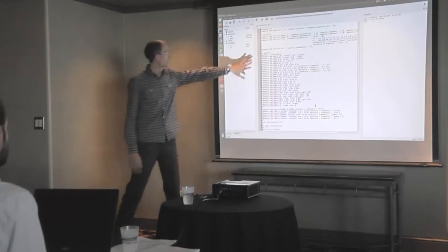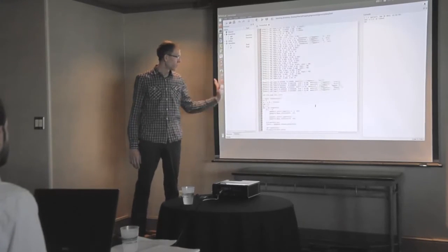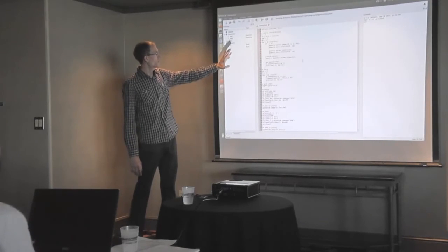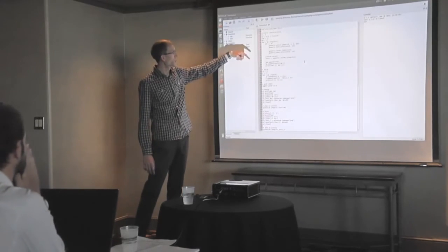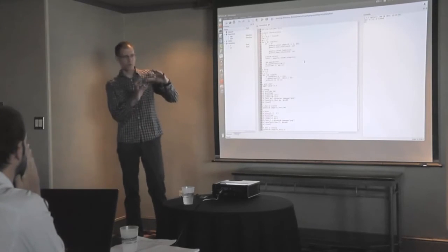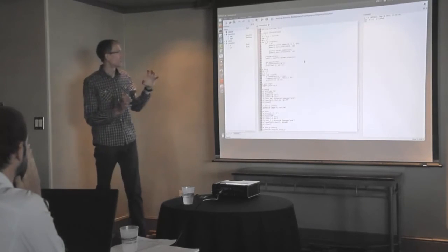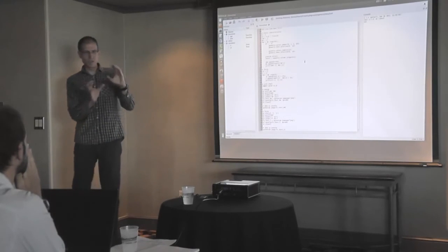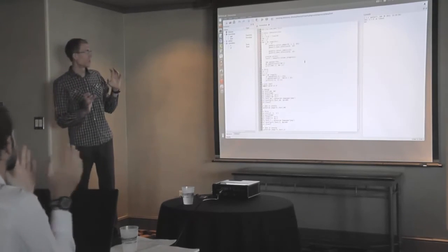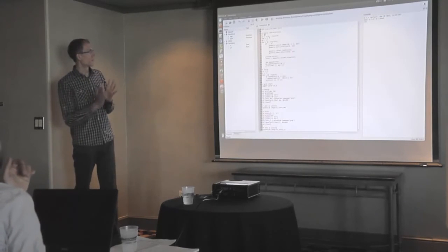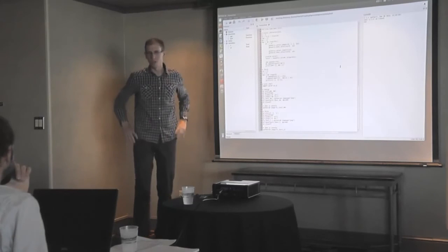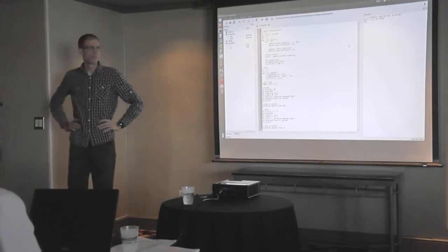Okay, here are points, edges, labels, and here is the script which uses a for cycle to move the armature. So we will calculate the total energy in, I think, 6 positions of the armature, and by taking the differential, we will calculate the force on the armature.